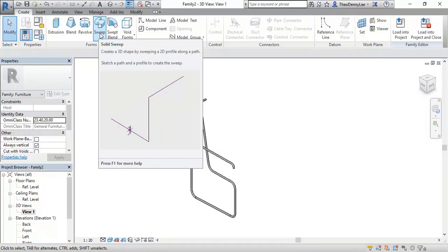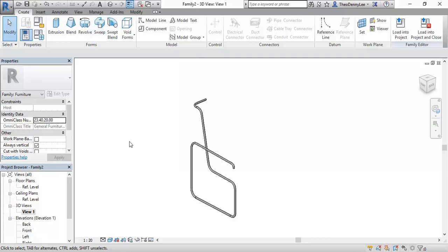Yeah, that's right. Capitals and cornices, yeah. Skirtings, that's right. Gutters, all of those things. Exactly. So you see them all the time in interiors, because all of those things that are standard elements in interiors can only be made with sweeps. You could make probably skirtings with extrusions, but you'd have to extrude in every direction around your rooms. Yeah, sweep's much better. That's right.